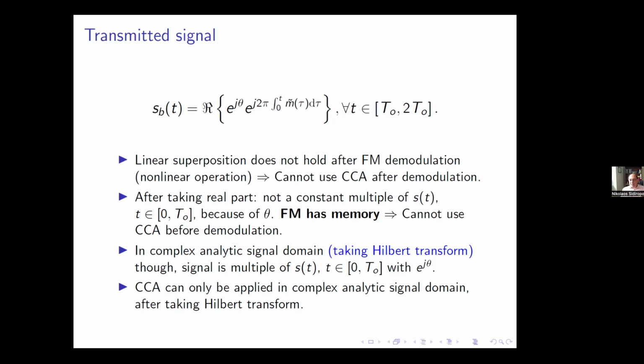So it posed a challenge for a moment, but soon after we realized that what we can do is work with a complex analytic signal. So if you use the Hilbert transform, let me take you back to your signals and systems days. You use the Hilbert transform, which basically is a filter that is 0 for all negative frequencies and 1 for all positive frequencies, or an approximation of that filter. When you use a Hilbert transform, you take a cosine and you map it to a complex exponential.